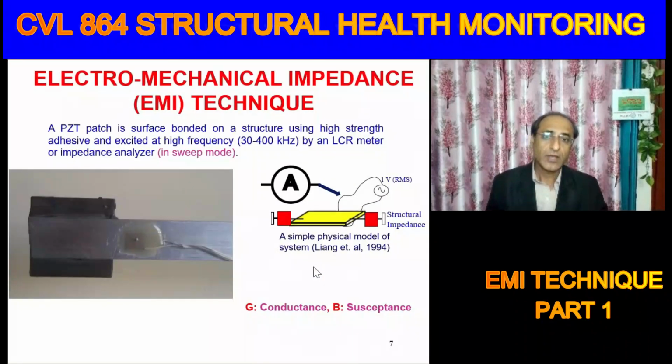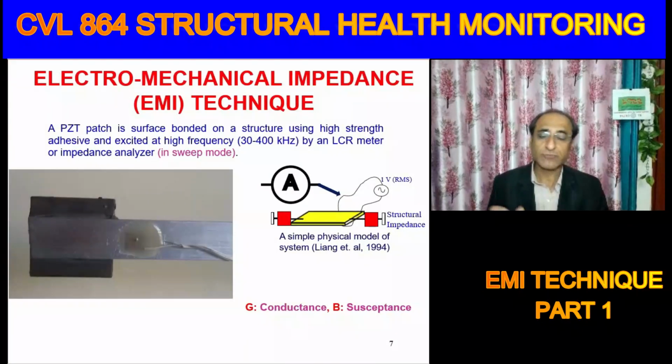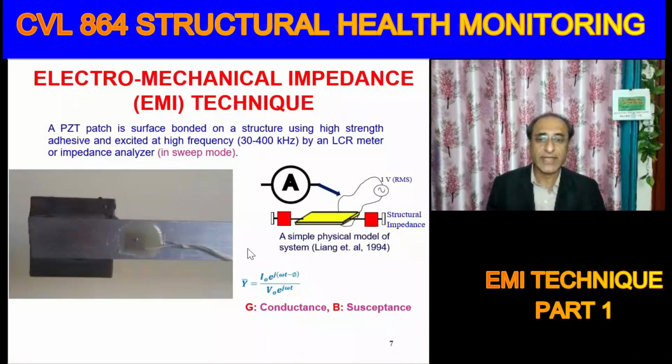But now the current and the voltage, they will not be in phase. There will always be some phase lag. For example, in the case of the mechanical vibrations also we have seen, whenever there are mechanical vibrations, there is a phase difference between the force and the displacement. So similarly here also there will be always a phase difference between the current and the applied voltage. So what we are doing is that we are finding out the admittance of the circuit.